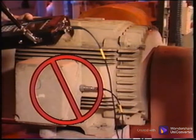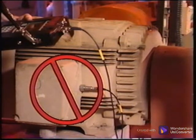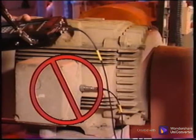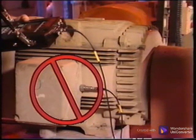Never use the electrical junction box for an axial measurement, even when it is a heavy casting of the motor housing. Data taken here will have higher levels of electrically related frequencies that may indicate motor problems that don't really exist.